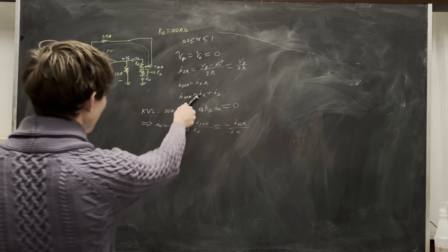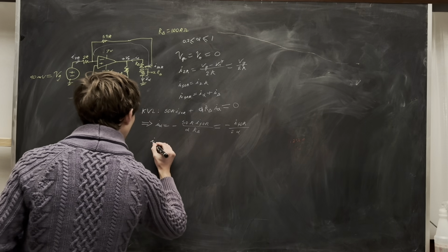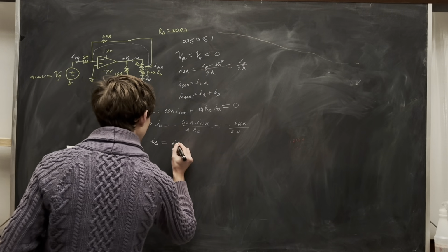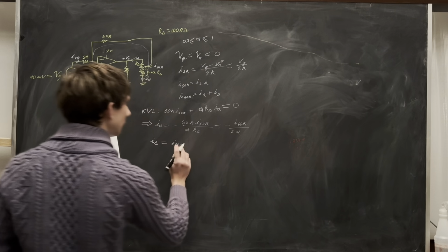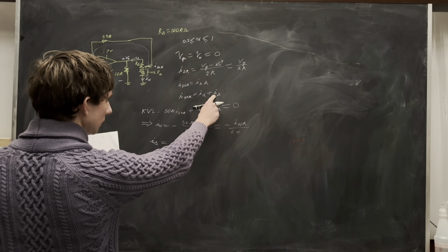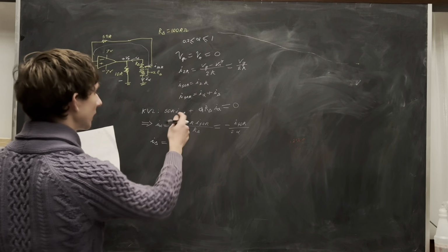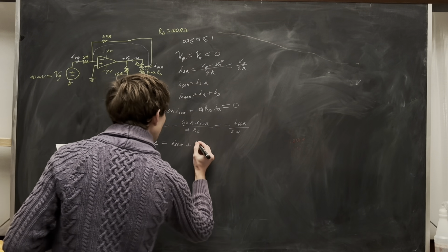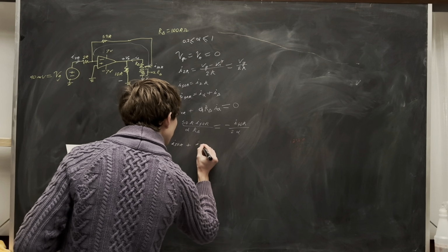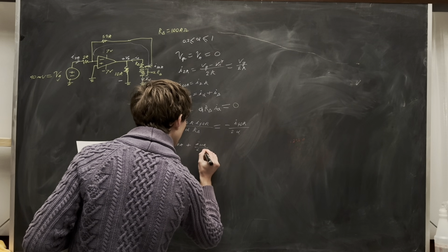So we'll just plug that back into here and solve for I delta. I delta is I50K. I'm again skipping a step here, but when you subtract I alpha from this side over here, it'll be negative, but that negative will cancel with this negative, so it'll just be plus I50K over 2 alpha.